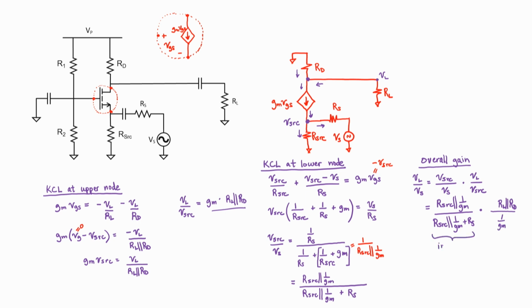The first expression looks like an input voltage divider, and the second expression looks like a gain expression. It's a ratio of two resistances. It's all of the resistances attached to the drain divided by some resistance associated with the transistor itself. It ought to remind you of the common base configuration. This would have been little Re had we been working with a bipolar transistor.